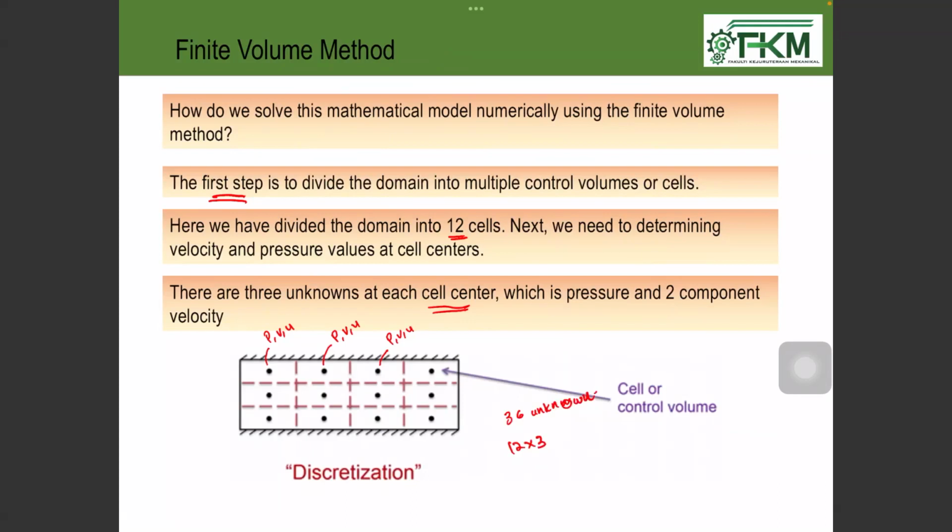For 3 equations we already use a calculator. For 36 equations, imagine how it would be. And the one earlier, someone made up to 200,000 cells. So you have 200,000 cells or elements, times 3 for pressure, velocity and velocity. But no, you cannot times 3, you need to times 5. You have velocity in x, y and z, and then pressure and temperature, so you have 5 for the mixing T problem. Like last Tuesday, so you need times 5, so it becomes 1 million.